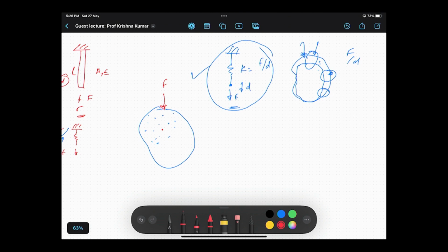So I'm going to say that all other guys, the red guys, are going to behave as dictated by the blue guys. What does it mean? I'm going to join and create regions. These are called elements. I'm going to join them and create regions, and so on. And I'm going to say that all the blue guys whom I have chosen are at the corner of these figures, these rectangles and triangles, and they have the full freedom to respond to the applied force. Then what happens to the rest of them? They are all my slaves. These guys only have degrees of freedom.